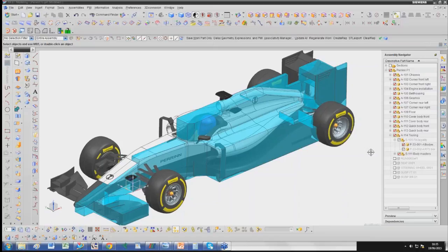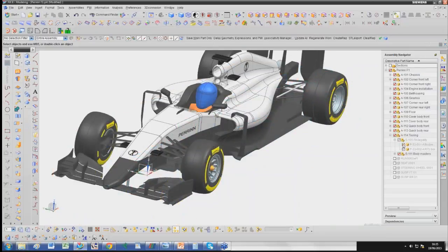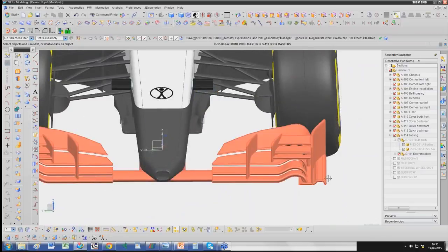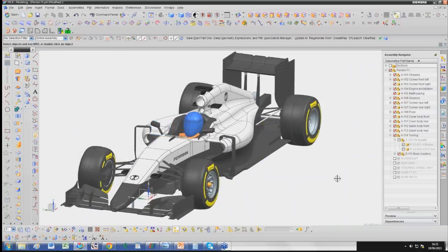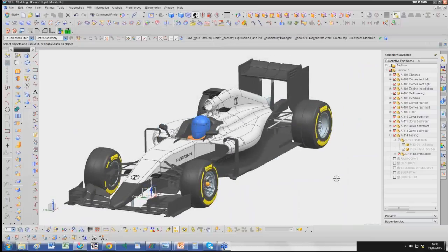I come back to the main one, the Y250. It's very simple to see that you go from this profile to a very loaded profile here, so that will create a vortex at the end of the wing. So you've got a lot of rotational flow happening here. On a road car, it's pretty much a very simple body with no discontinuity. It's like a big box. So you don't have as much vorticity happening. And if it happens, it's not really studied as much. So to answer the question, it's much, much less, if not at all, studied for road cars.